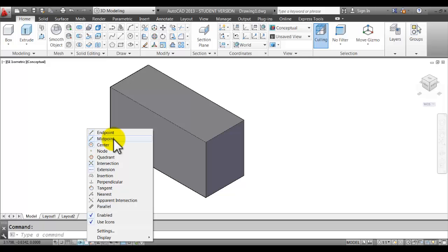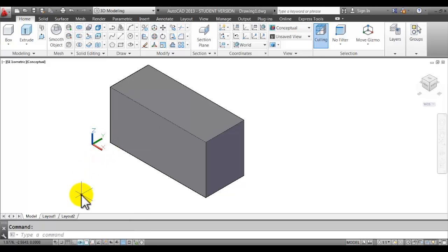I'll go ahead and use my escape key to get this menu out of here. And make sure that that 6th icon is actually blue so that you kept it on there at the bottom left. Also, the other icon that we're going to be working with is called Allow Disallow Dynamic UCS. It looks like a little L shape with a yellow lightning bolt, and what that does is it allows us to draw on this face of the cube.